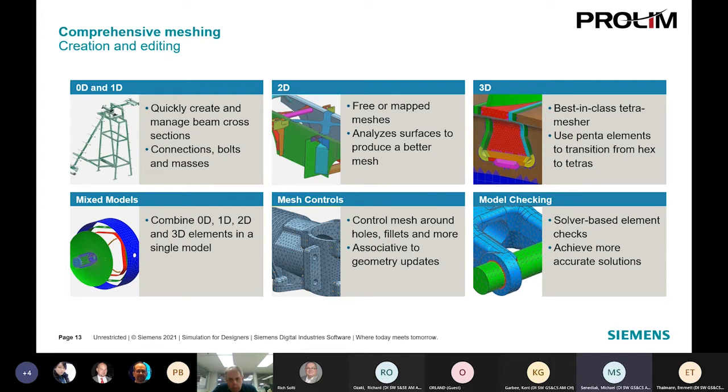2D meshing, where you may have, like we talked about, the sheet metal parts, where you would do the mid surface for that, or you could also use what we call a mapped mesh that will help guide the 3D mesh to small blends, certain areas of the model that you want to refine. And then, for a designer, many times you might be working in one or sometimes you would be in mixed models, right? You need a little bit of each of those mesh capabilities. And that's something that you don't always see in other designer level tools, having that capability to do all of that work.